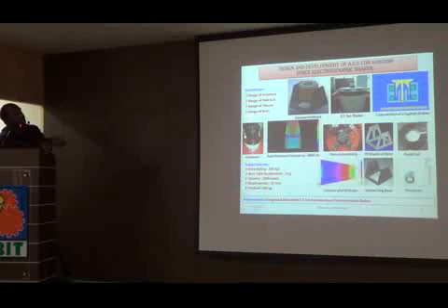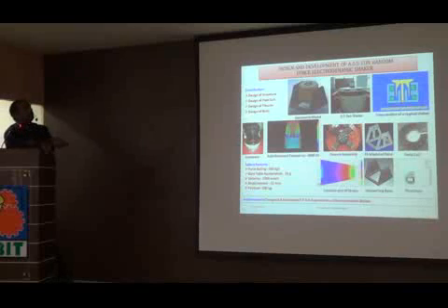Similarly, field coils are required to give a magnetic flux density of around 1.5 Tesla in the narrow gap. So accordingly we have studied and then designed. Then you need the magnetic body, or the pole we call, the center pole and the outer pole. That has to be designed. Then the conductor needs to be guided by something called flexures, which allow motion in the vertical direction but restrain the other two, meaning it should have more lateral stiffness and less axial stiffness. So it should be designed in such a way. We designed as per these specifications, and yes, we did test it and it is also good.